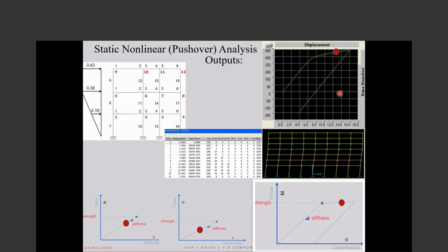We say, okay, let's try another earthquake. So this building, it seems, can't withstand, for example, the earthquake with 2% possibility in 50 years. Try it with 10% in 50 years. Ordinary design level earthquake. So, for example, for that, this building is around 13 centimeters. So the software begins to push the building.